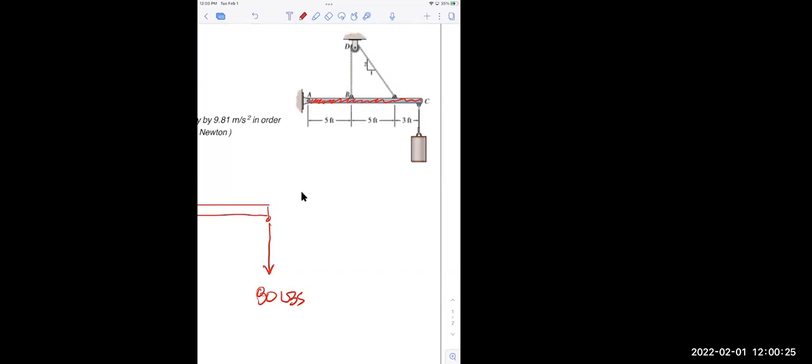Where would that 42 pounds act? I mean, it weighs 42 pounds, but remember, some of its weight is here, like there's 10 pounds, and there's 10 pounds, and there's 10 pounds. It's got weight everywhere across it. Does it make sense that really this is a continuous load all the way across this thing? There's actually arrows everywhere up there.